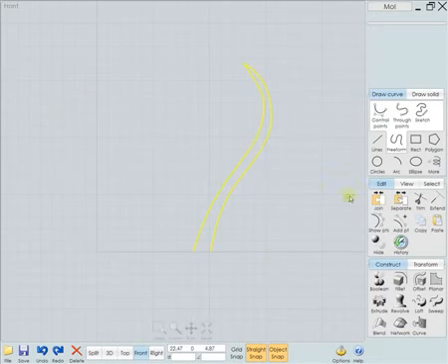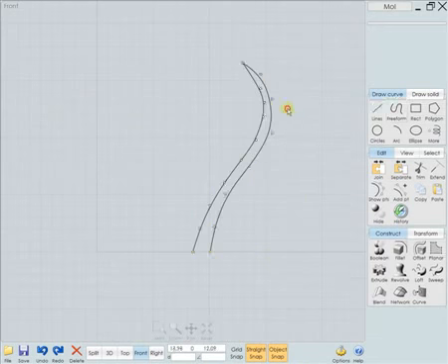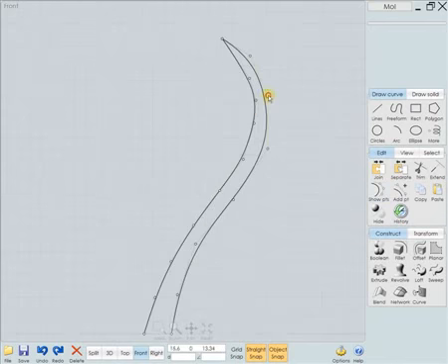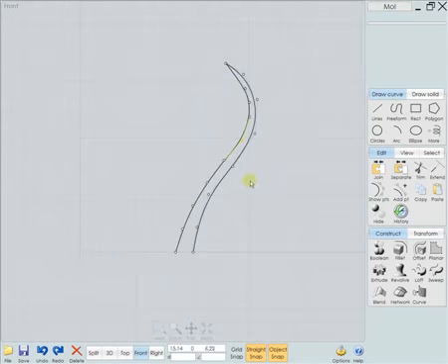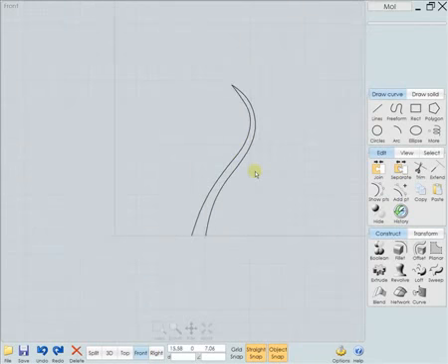So in this case, I'll go from the right to left and I'll say show points. I'll just edit these a little bit to smooth things out. And I'll just call that good for now. I'll turn off points by clicking on the escape key on the keyboard. One tap of escape deselects everything. The second tap will turn points off.